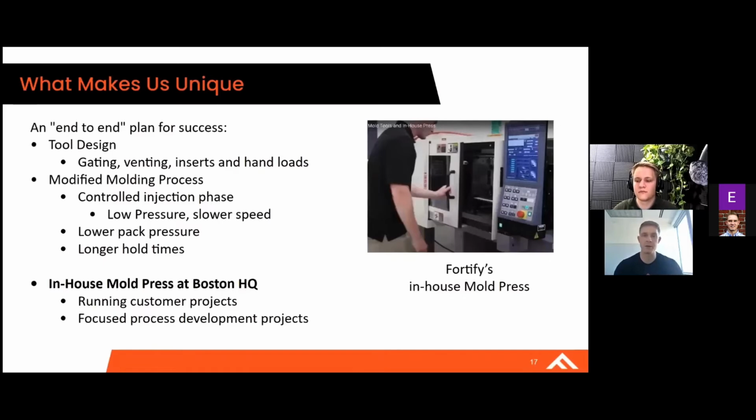We pair all that with a really deep understanding of the applications that we're going after. So in this case, injection molding. We have brought in-house an injection molder that we're using day in and day out, print our tools, test them out, make changes, do all that great stuff. What we found is that printed injection molds are just not quite the same as standard metal molds. You treat them a little differently, and they're going to treat you very well.